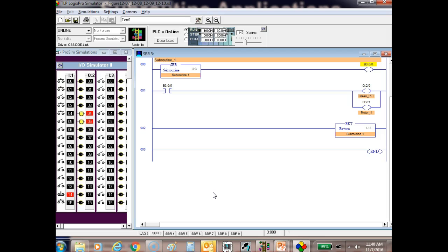And people new to PLCs think they've always got to use a what? They think they always have to use an output. They think you've got to have an output over there. But if those contacts don't need to generate an output, then you need to get used to using your B3s and what's the other? B10. Some even support more.